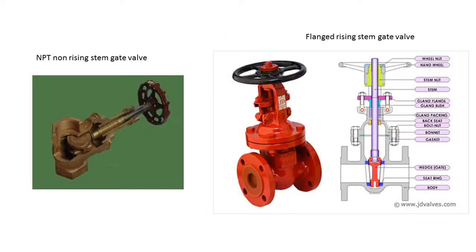These valves are called gate valves. They operate by lifting a round or rectangular gate or wedge out of the path of the fluid to be controlled. Gate valves are primarily used to permit the flow of fluids. A typical gate valve should never be used for throttling purposes, only for on and off. Throttling will cause premature valve failure.